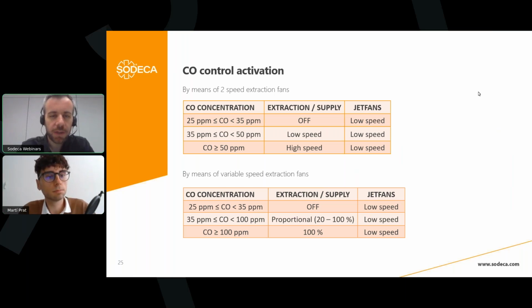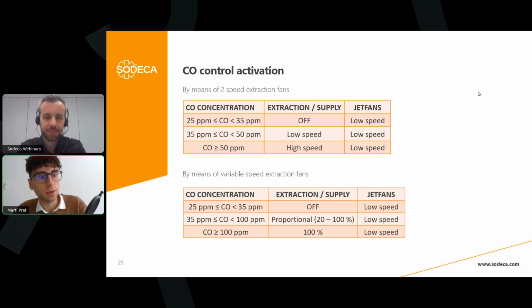Okay, we have more questions related with CFD analysis. Is there need of a CFD analysis to simulate the smoke extraction in a basement, or if we design as per code requirements, will our design be considered safe? That's a good question. Technically, if you follow the standard and you make a good design that you know will work, it wouldn't be necessary. The CFD is mainly to reinforce that it is a good design, but it is not something mandatory, at least right now.